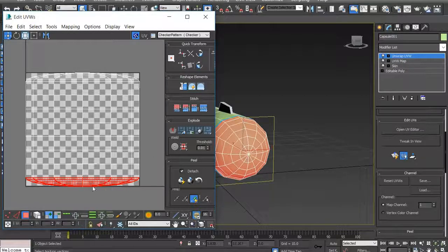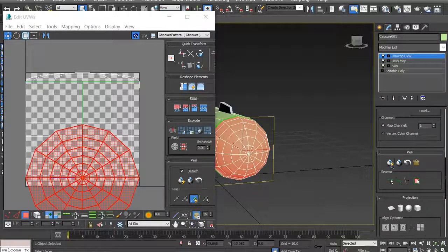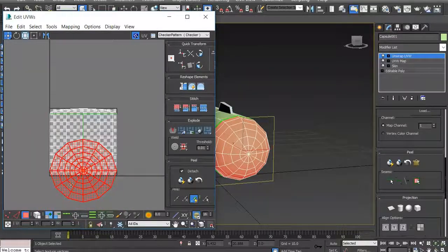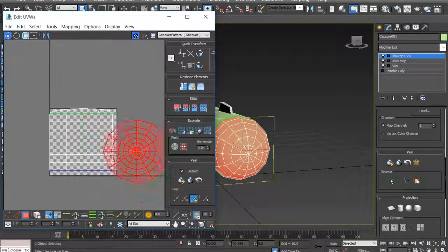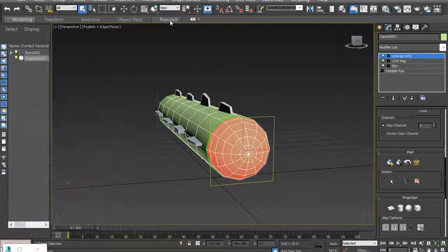So we need to convert this, which is currently all these red shapes down here, into a flat form on here. So we go back down to quick peel, and we just hit quick peel, and it automatically gets all those objects, flips them, and aligns them in a way that's useful for us. And you can see that they're not tied to those other objects, and that's because we disjointed them with the edges. The blue line edges that we created made this so that they're not connected to the other pieces here somehow, at least graphically on the bitmap. Okay, so we'll minimize that for a sec.